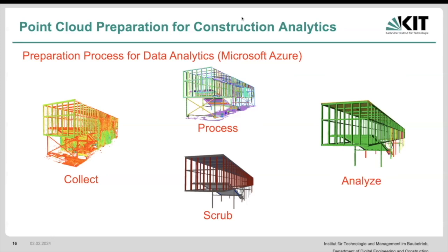Then you have to process this. That means that you have to summarize this information as much as possible to what we want. In this case, for instance, I have a bunch of planar surfaces. I need a process to automatically extract planar surfaces from these point clouds. And now my point cloud has been summarized into a set of planar surfaces with some boundaries around. Okay?